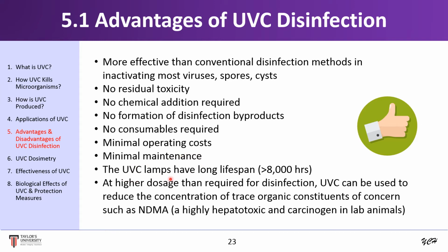The UVC lamps have a long lifespan, usually more than 8,000 hours, and also a higher dosage than required for disinfection. UVC can be used to reduce the concentration of trace organic constituents of concern such as NDMA. NDMA is highly hepatotoxic and a carcinogen in laboratory animals.